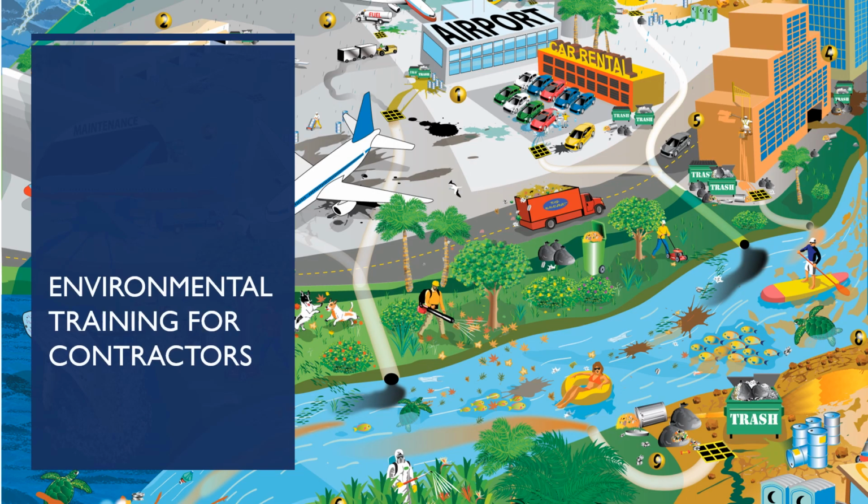Stormwater runoff can pick up harmful pollutants and deposit them into drainage systems, streams, and the ocean. Construction activities may be sources of potential pollutants such as sediment, concrete waste, vehicle and equipment fluids, material and chemical spills, lavatory waste, and trash. Stormwater is typically not treated after reaching the storm drainage system, which means pollutants could have the potential to reach our streams and oceans. On-site pollutants can also contaminate the soil and groundwater. Help keep our environment clean by implementing the BMPs discussed in this training.